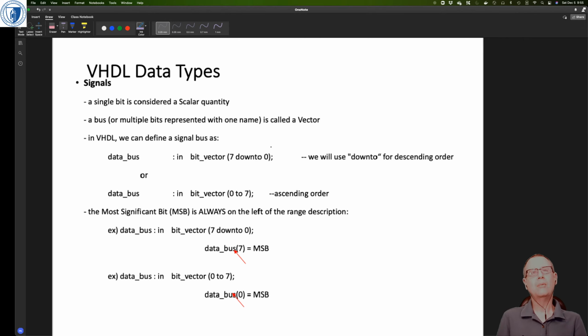Okay, and std logic is just a single Boolean value, but usually we want buses or vectors or values with more than one bit. So there are different vector quantities. This is the standard way of doing it in VHDL, but we've mostly used std logic vector.